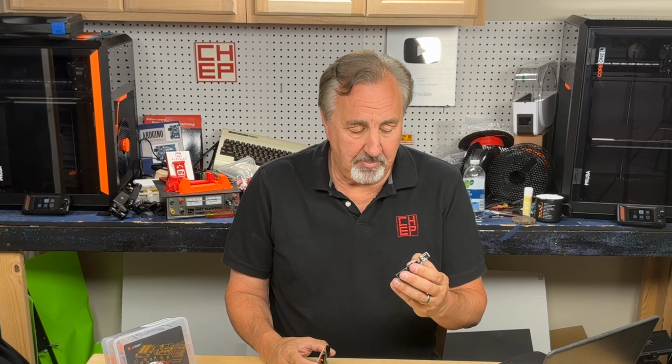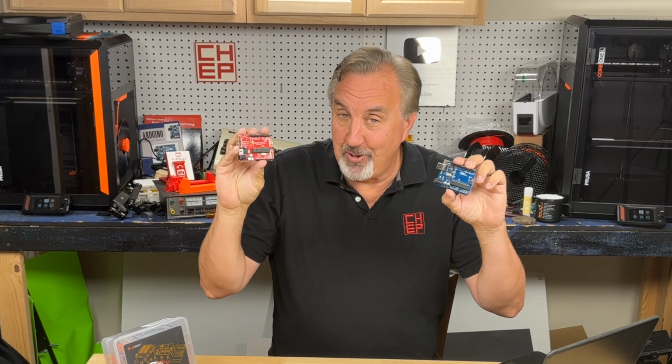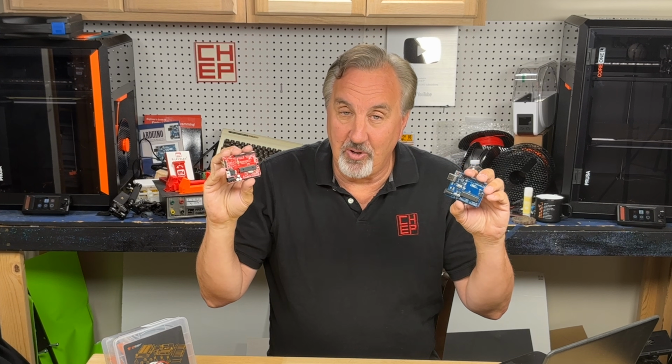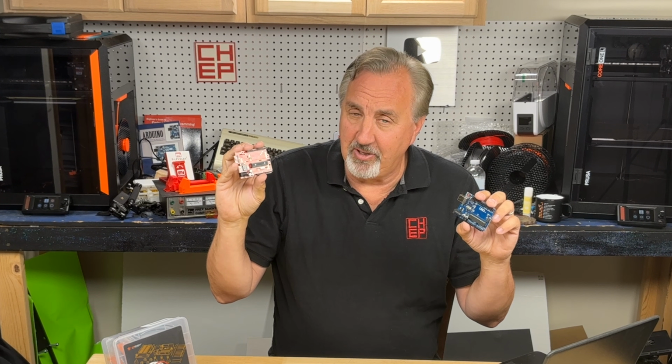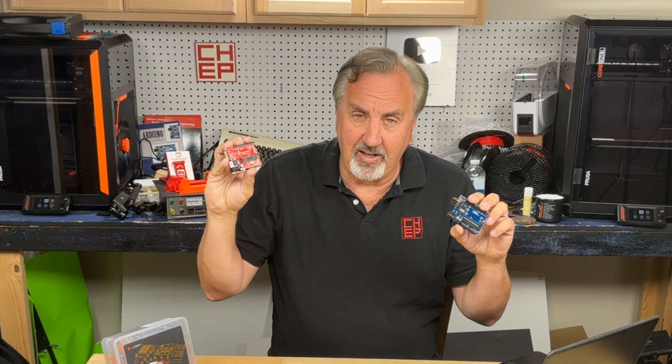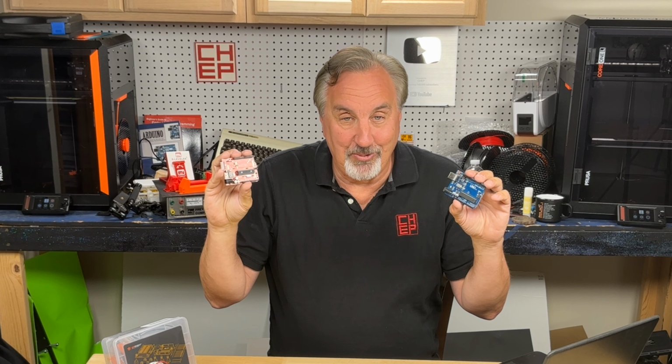What I like most about the GCBASIC compiler is I can program both AVR or the Arduino, but also PIC microcontrollers like my CHIPINO. So I can go through 2 different microcontroller families and use the same code. In fact, this LCD thing, I could run it on the CHIPINO, totally different micro, but all I have to do is change like 3 lines. At the top, I define it to the PIC 16F886 and also 2 different connections on the board itself. Other than that, it's identical and runs.